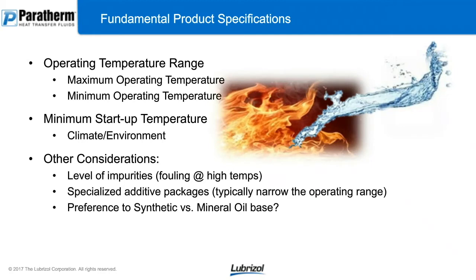Another key fundamental specification is your minimum startup temperature. Now, you need to take your climate and your environment into account for this property. You want to make sure that if you're operating in a very cold environment where you need to start the system up at some cold temperatures, your fluid is able to be pumped at that temperature. So obviously, as you would imagine, there are going to be some trade-offs between how high your fluid can go versus how low your startup temperature can go. You need to make sure that you specify a fluid that can handle your entire temperature range.